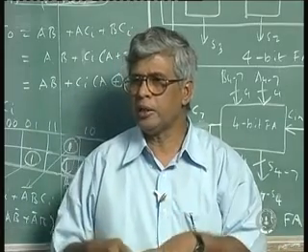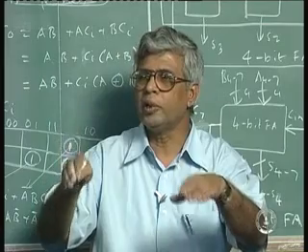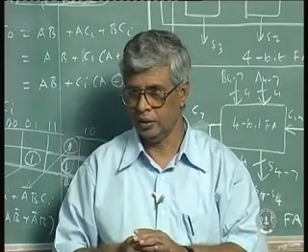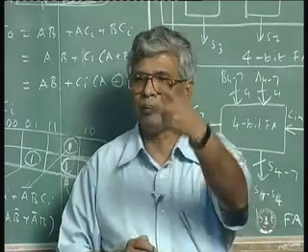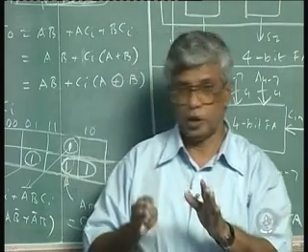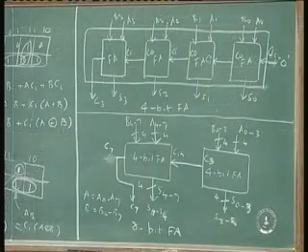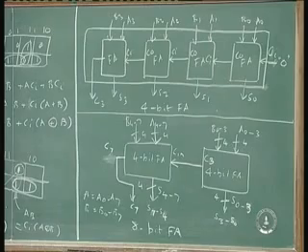So the total propagation delay is 16 carry propagation delays. The carry delay of a full adder is the carry propagation delay. 16 of them have to be used. It's just a 16-bit adder. It could be a 32-bit adder, 64-bit adder, you can imagine.